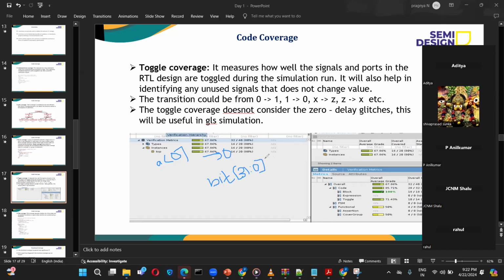Only the simulator will check that. The simulator will check how many bins are covered. If for example out of 65,535, only 40,000 are covered, and the remaining 20,000 are not covered, is it possible to check which 20,000 are not covered?